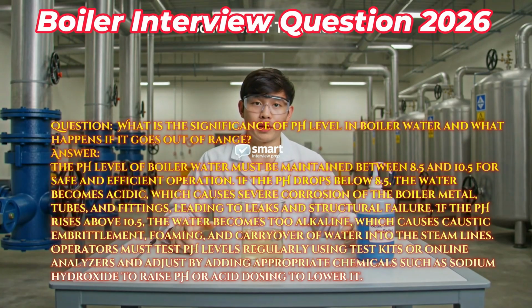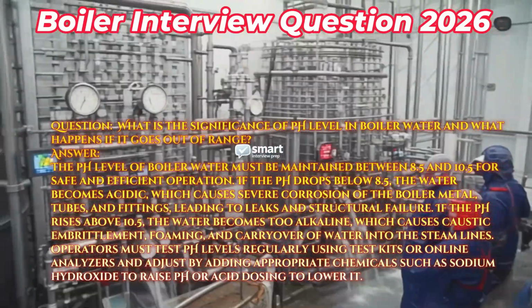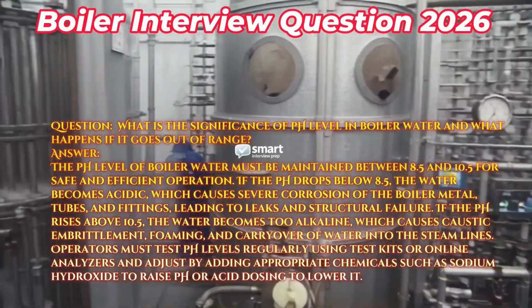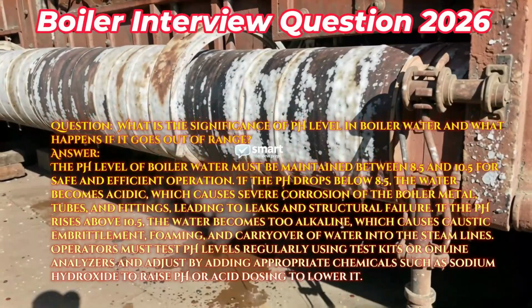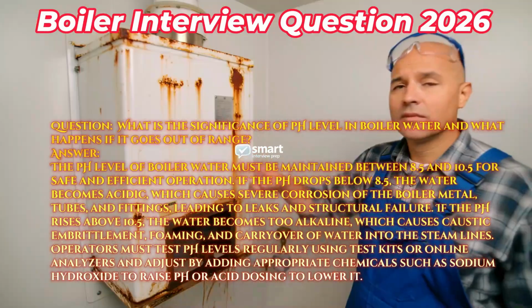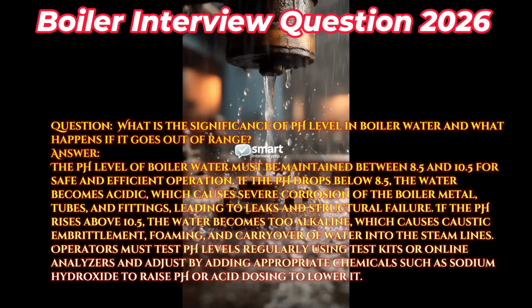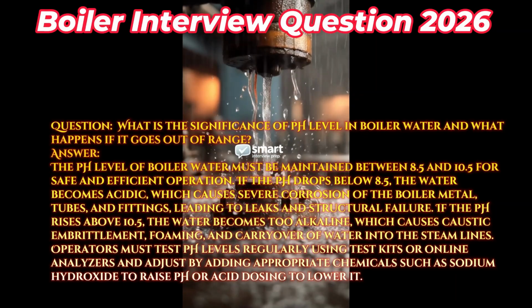Question: what is the significance of pH level in boiler water and what happens if it goes out of range? Answer: the pH level of boiler water must be maintained between 8.5 and 10.5 for safe and efficient operation. If the pH drops below 8.5, the water becomes acidic, which causes severe corrosion of the boiler metal, tubes, and fittings, leading to leaks and structural failure.